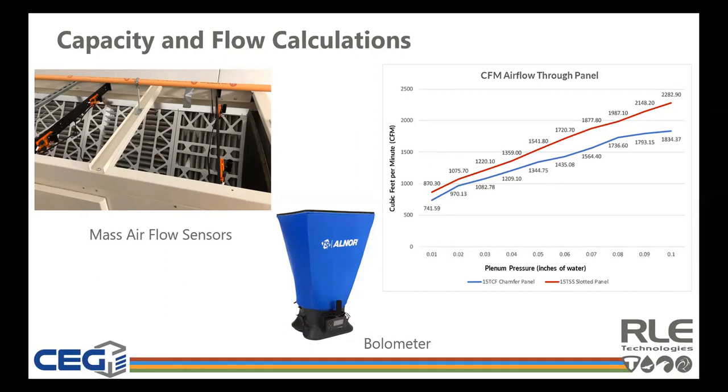You would then refer to your floor tile manufacturer's specifications and ratings for the perf tiles to make sure you're selecting the type, the quantity, and the right tiles that can deliver that amount of CFM. So now you're going to come back to this kind of chart. You've got a spec sheet on perf tiles from whoever you're looking at, and usually you've got some performance metrics and graphs on that spec sheet that are going to help you make this decision.